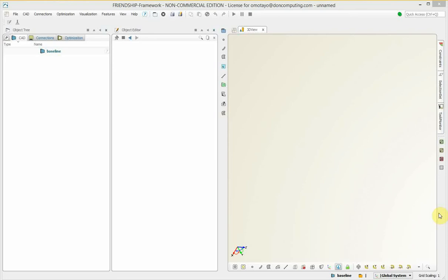Another tutorial will show you how to generate advanced parametric surfaces using these kinds of parametric 2D definitions. In the first step, a NURBS curve is created based on 3 points, so-called control vertices, since we want to utilize the weights of a NURBS curve. The weight controls how much the curve is attracted to a corresponding control vertex.